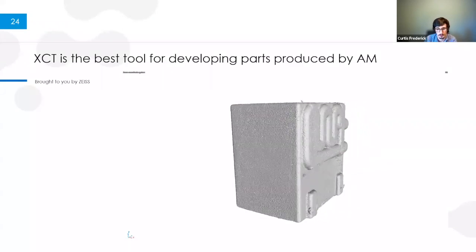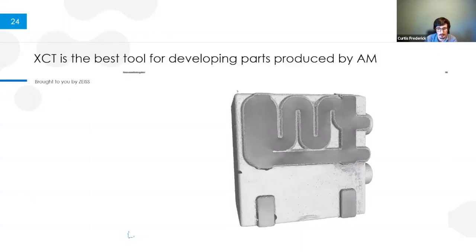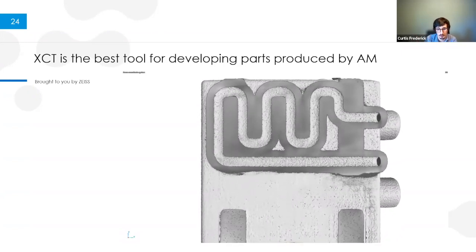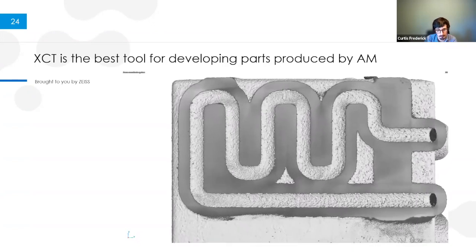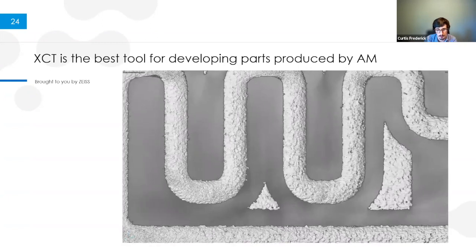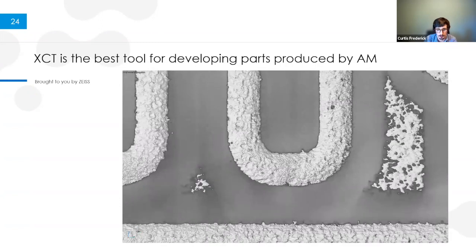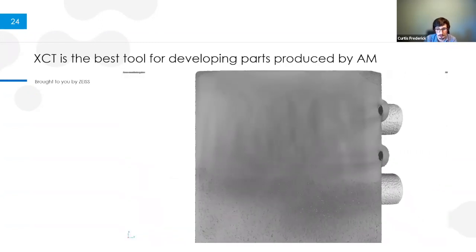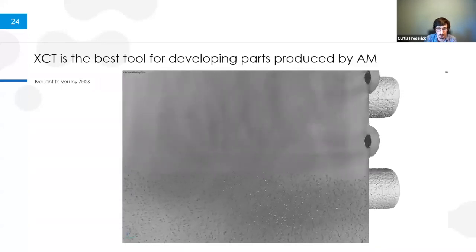Because it's an X-ray CT model or a volume here, we can slice through any plane. We begin to slice from that one face to look inside the channels. You can see that the as-printed surface looks really rough here. This is a little bit exaggerated because of how X-ray CT picks up the surfaces, but it is also something we can improve in future work. We didn't optimize the surface roughness. We're mainly controlling that higher density in the region around the channels and allowing lower density and faster parameters in non-critical regions.